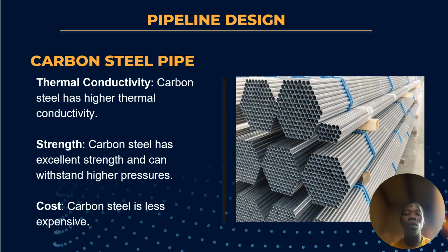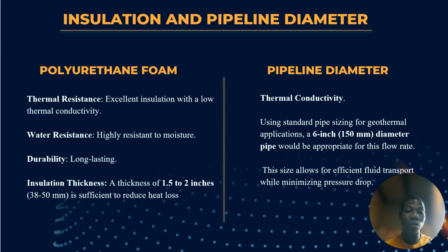So we need to conduct whatever heat we are generating into the already existing system to operate. We chose carbon steel because it has high thermal conductivity, excellent strength, and can withstand high pressure. So that was the reason.